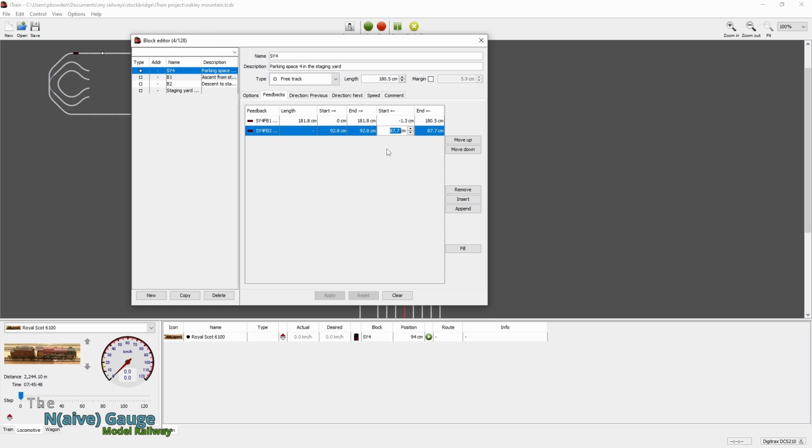875 millimeters. I've added an extra 2 millimeters because I measured along the outside of the inside rail rather than the center line. So I need an extra little bit of fudge factor just to account for that. And I've calculated that should be around about 2 millimeters. And so here I'm saying it's 877 millimeters between the optical detector and the end of the run, and so this is the distance from the start if we're heading in the opposite direction.